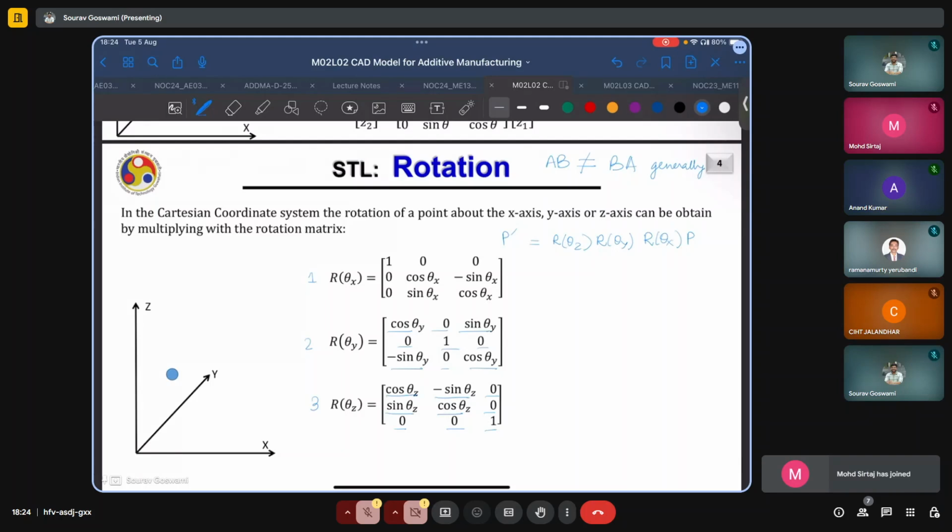Secondly, from a vector mechanics point of view, we are already familiar with the fact that finite rotations are not a vector operation. That is, the order will matter. If I rotate an object first about x, then y, then z, and I repeat the same operation, keeping the values of those rotations the same but changing the order, say now first rotating about the z-axis, then about the x and the y-axis, the final orientation will not be the same in both of these cases.